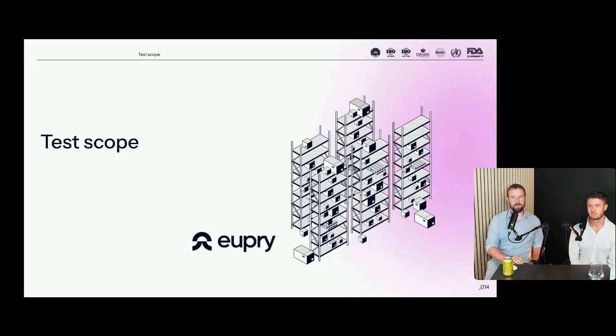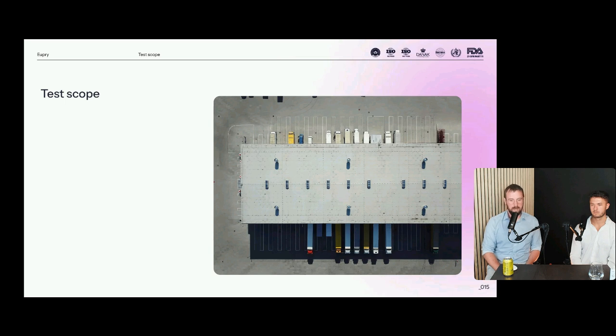So moving on to the next point here, where risk-based approaches is really relevant, is in terms of the test scope. A test scope would often involve, do we need to perform summer and winter mapping? I think we touched base on this early on as well. It's crucial to identify whether summer and winter will have an impact on the stability, homogeneity, and conformance of your temperatures.